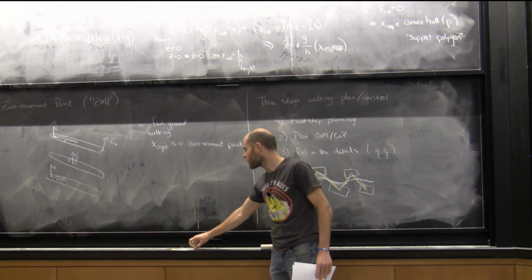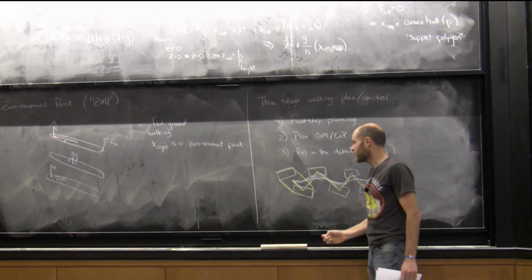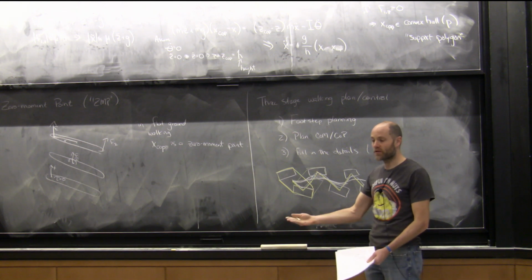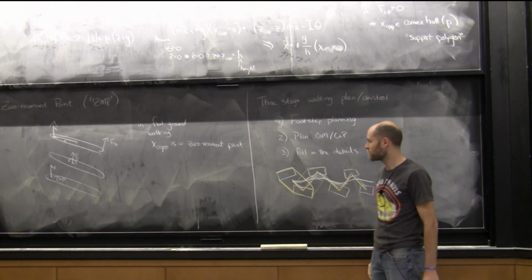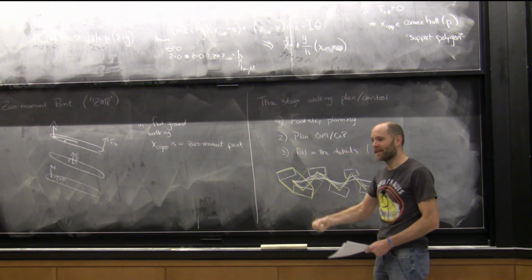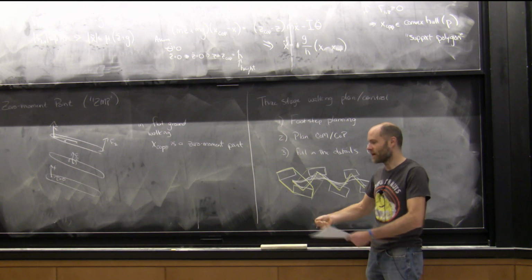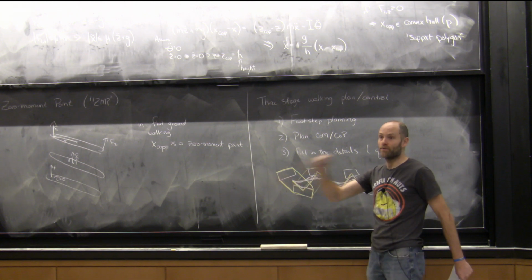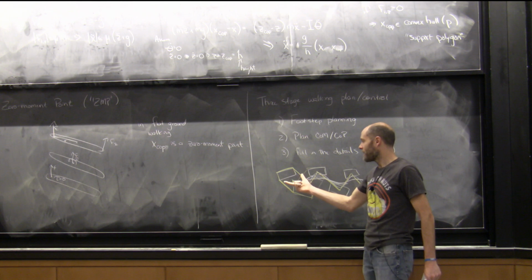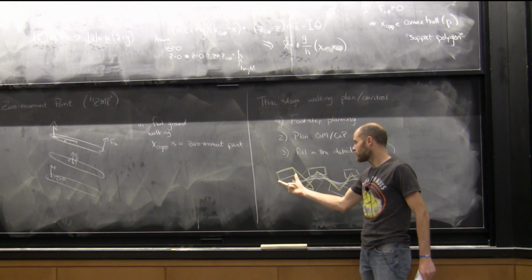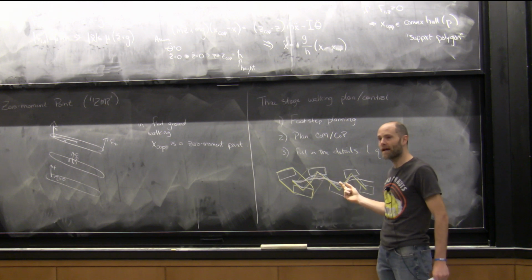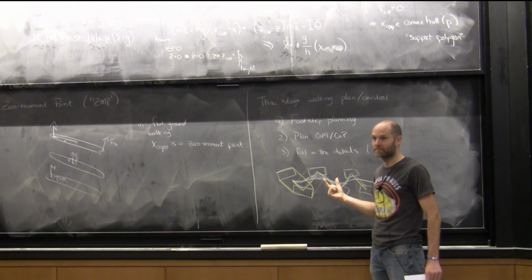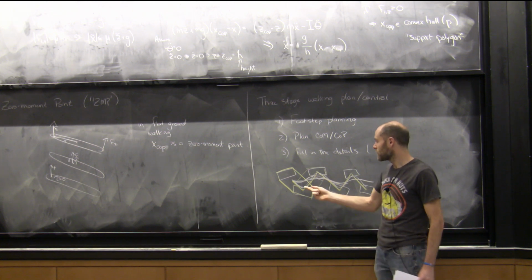So I'll give you the automated one that we've done. In the past, robots walked on flat terrain for a long time, and then they walked on stairs or other things where it was pretty natural to put down footstep plans. When we started the DARPA challenge, we made a GUI to allow people to put down footsteps, and we increasingly got more sophisticated about doing the footstep planning. I think most people today still plan their footsteps relatively independent of the center of mass, but we have ways to combine a little bit of the dynamics of the center of mass in the footstep plan, and I'll show you that in a moment.